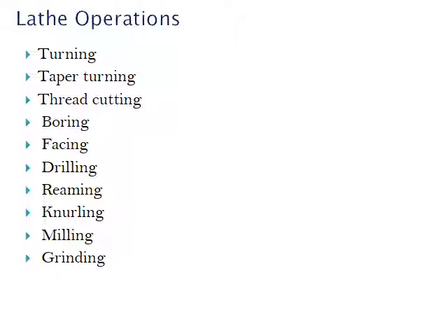Capital D is the major diameter of the taper, and small d is the minor diameter of the taper, not the job diameter. Don't confuse. I am only discussing the tapered area. Suppose the job is 100 mm, and in that a 20 mm length is tapered. Taper means it is not a straight line, it is a conical shape.